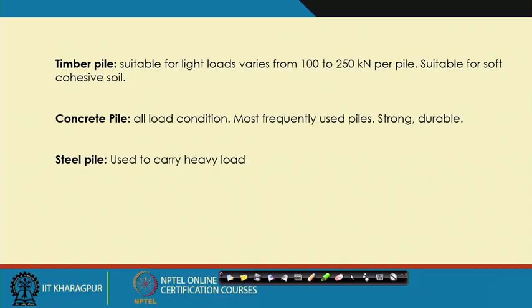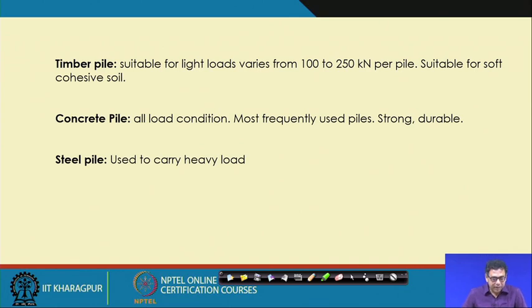But if the soil is very hard, then these timber piles may be damaged, because your soil is very stiff and you are applying the driving force. So, there is a possibility these piles can be damaged. So, if it is a cohesive soil or a less loaded pile, then we can use the timber pile.